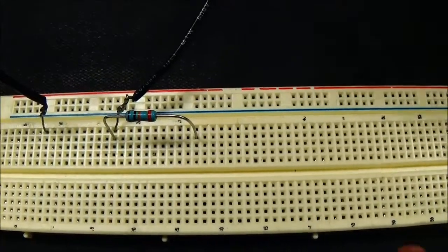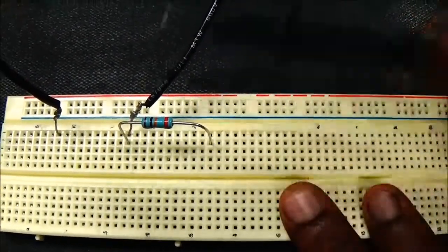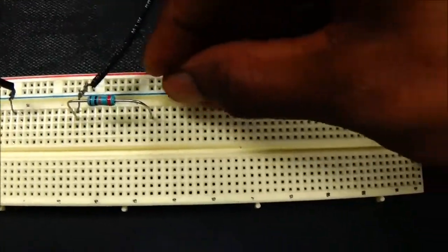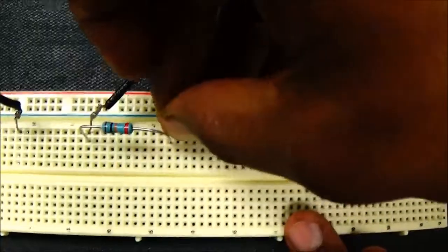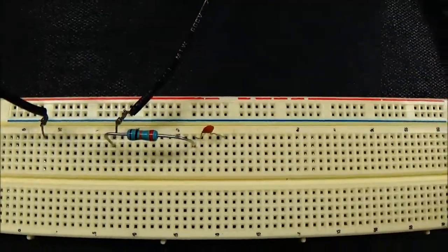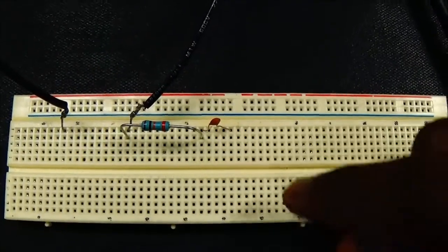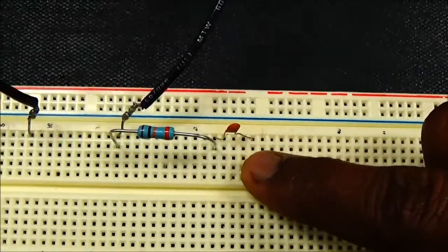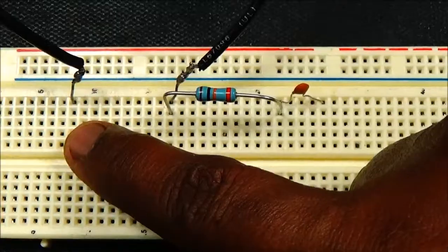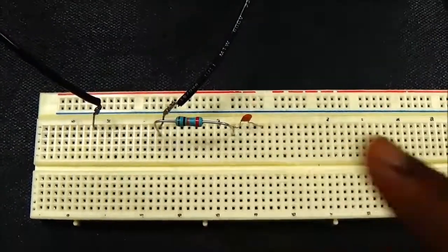Do you see? They are in the same line for getting the series connection. Now is the capacitor that should go in line with the second end of the resistor, like this. Now all the three components are connected in series. Now I am going to use some hookup wires to connect to the second end of the capacitor and the first end of the inductor so that I could connect it to the function generator.